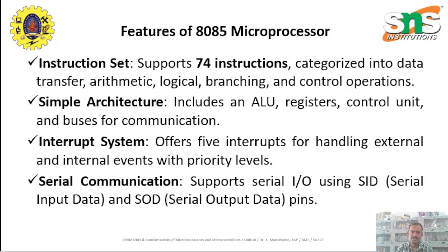And it supports an interrupt system. It offers 5 interrupt sources for handling external and internal interrupts. Also we can set a priority. So both internal and external interrupts are available. We have RST 5.5, 6.5 and TRAP. These are the external interrupts.